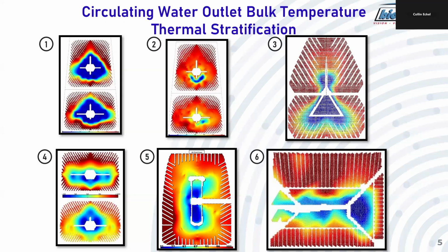Images 1 and 2 are the same condenser. Image 1 has high air leakage, and image 2 has low air leakage. The difference between the dark red and the dark blue on this image is approximately 30 degrees Fahrenheit. And these two images are interesting because they show the different ways air is stored within the condenser tube bundle. We refer to these two ways as either a stagnant zone or an air-bound zone.